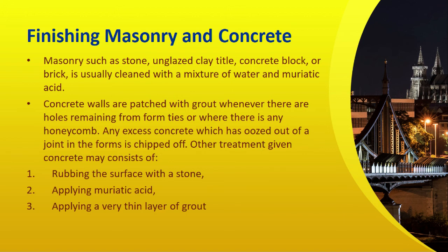Finishing masonry and concrete. Masonry such as stone, unglazed clay tile, concrete block, or brick is usually cleaned with a mixture of water and muriatic acid. Also, any excess mortar is removed.